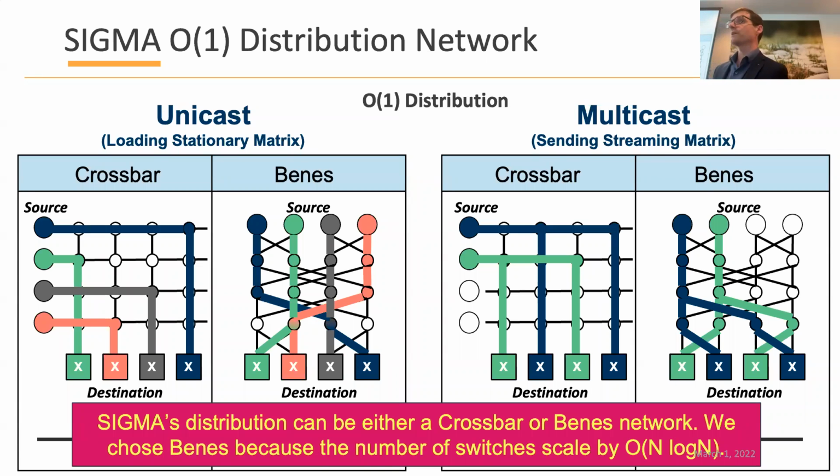The configuration depends just on the dataflow, and you run it at the beginning of a layer. We are mapping layer by layer. So for one particular layer you configure first, and then you run it. And then you configure the second layer, or you can leverage the configuration of the first layer to run the second one. Since the layers are typically very large, you are amortizing all of this configuration step.